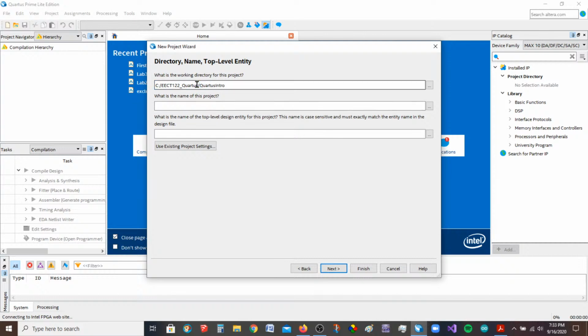All right? I don't want to just smash everything together here. What happens is you'll have a bunch of files named waveform.vwf, because that's what you have to call all of your vector waveform files. And you'll have all of that stuff kind of crammed in the same place. And it's hard to get to the actual lab that you want to get to. And Quartus, when it looks back into this folder and it goes to run the vector waveform file, sometimes it'll run a different project altogether. So if you have everything quartered off and you have everything in its own specific folder, Quartus won't have any issue with it.